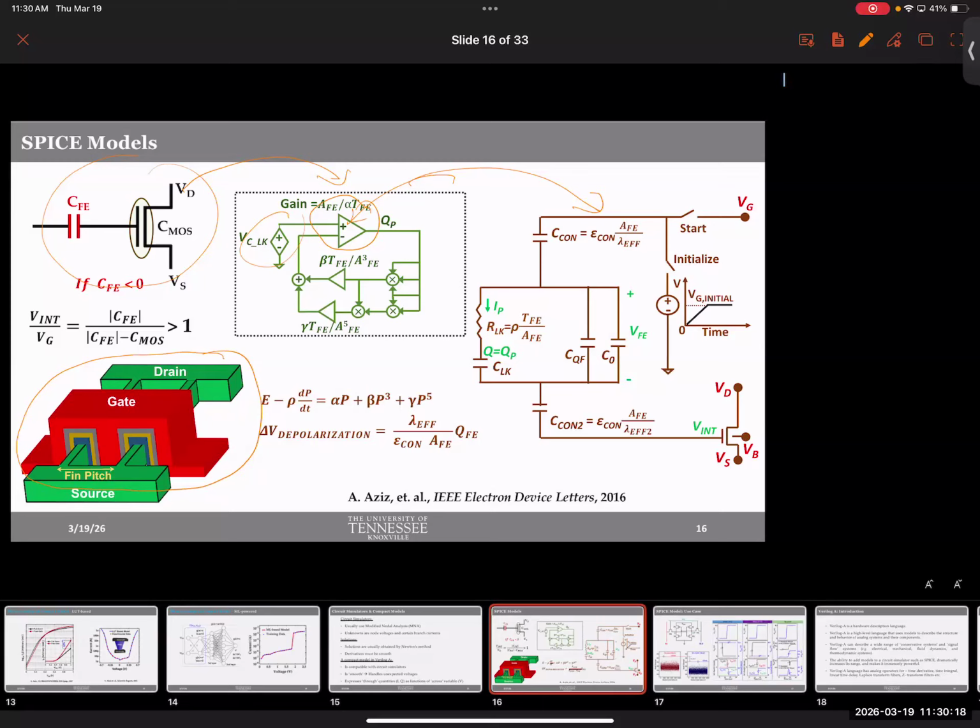And oftentimes they tend to converge quickly because SPICE is a very efficient circuit solver. And when you're expressing this in circuits, by the way, there are other advantages. You don't have to worry about expressing the characteristics and properties in closed form equations. Maybe if the equations are so difficult, especially if it requires numerical solutions, then Verilog-A compact modeling can become tough, right? For that, circuit simulators are often the places to be.